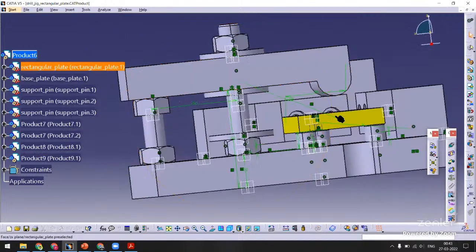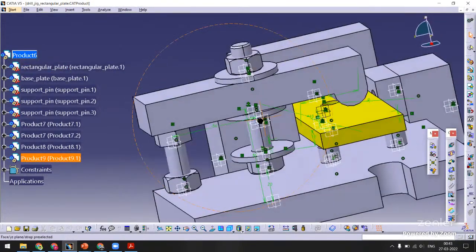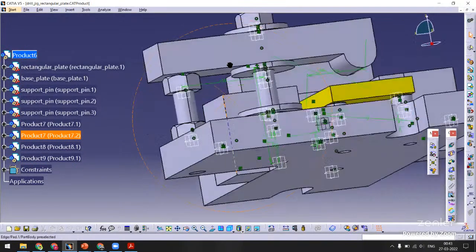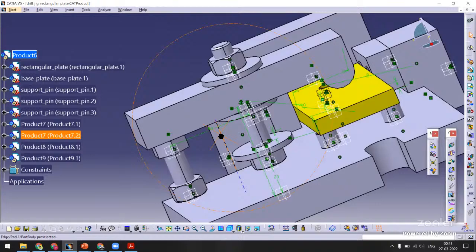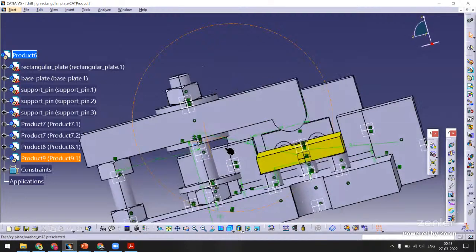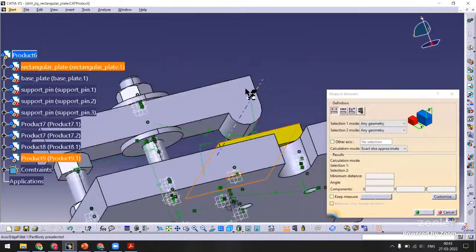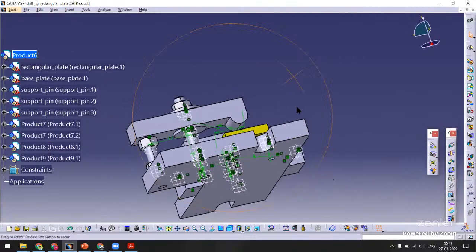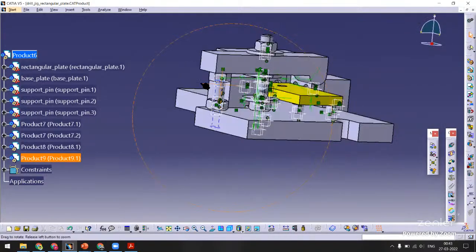Everything is looking good, but it is not clamping. The clamp is not clamping the workpiece, right? So we need to bring the strap still down. It can't be at such a height, right? Let us measure what is the distance quickly. So the distance from the top of the workpiece to, so this is 10 mm. So we need to bring everything down by 10 mm. I think it's possible. Yes, possible. Why not?